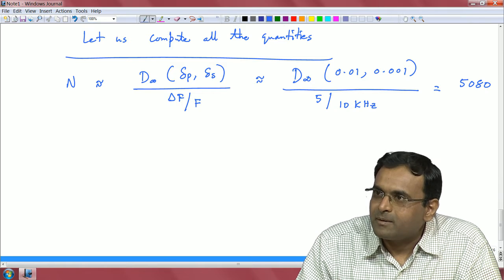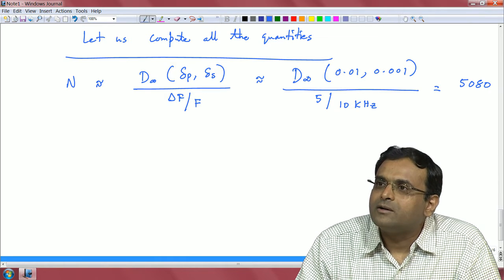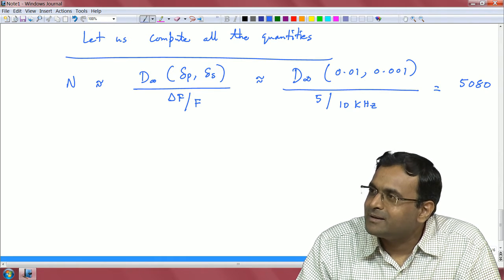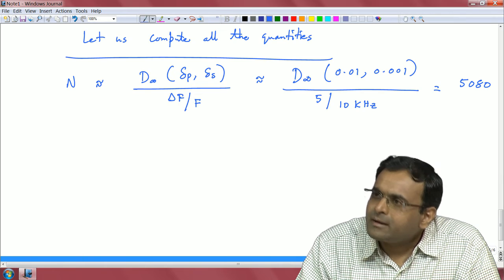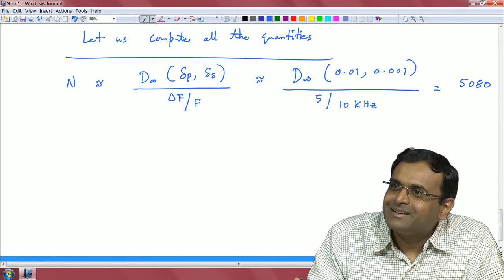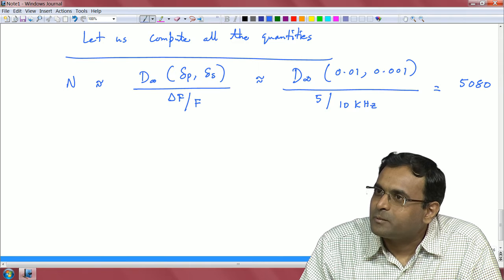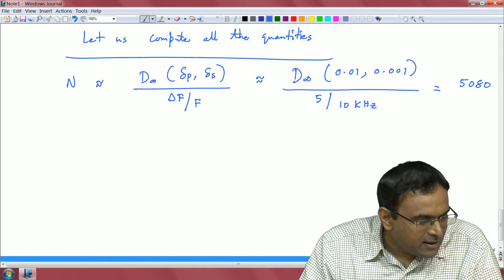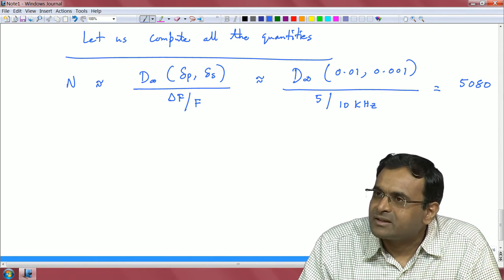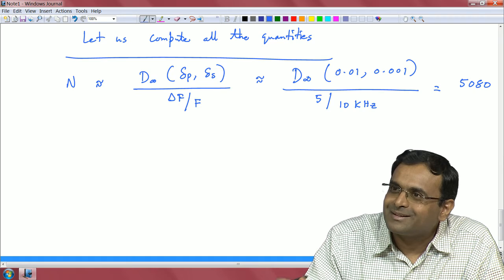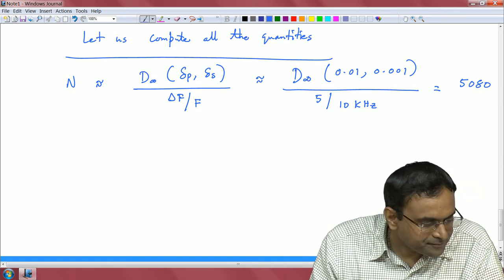This is a practical problem, right. I had a 10 kilohertz signal and I wanted to downsample it by 100 and I have very narrow transition band of 5 hertz, and if I did all the math, this is what I will land up with. So, now you can imagine the latencies etc. that this filter will cause if you were to implement them.